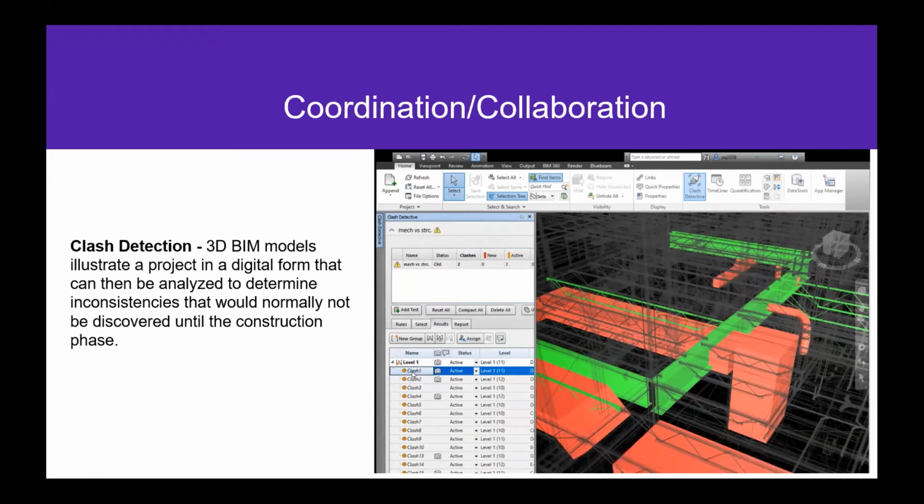In a case study I read, such conflicts can drive the cost up to $1.2 million, because if you face this right in the field, you have to lower this ducting, which means you need to lower your ceiling, which means the owner is going to lose clearance height, and they might not be happy. So all the rework and so on is going to cause extra cost to the owner.